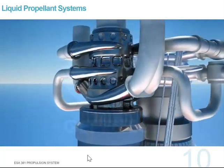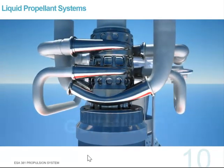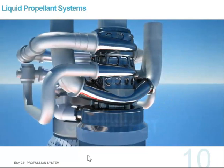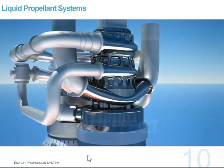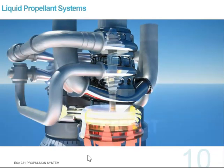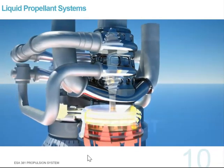The huge flow rates of oxidizer and propellant required in each engine were provided by the turbo pump, a device composed of 2 high-pressure pumps and a turbine, interconnected by a same shaft. The turbine converted the thermal energy from the gas generator's hot exhaust into mechanical energy, to rotate the shaft, which in turn drove the pumps.